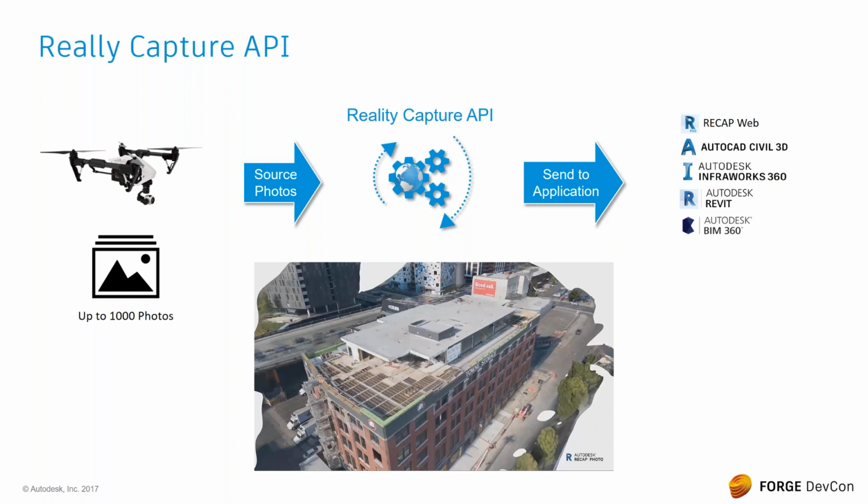So if you're flying your UAV over and taking pictures of, for example, a site, you can mark a ground control point of a known location, and then that will help geographically locate the model that comes out of the calculation of photos to 3D mesh and give you an extremely accurate representation of not just the model physically, but also the model geographically. So you can start locating other assets in relation to that model.